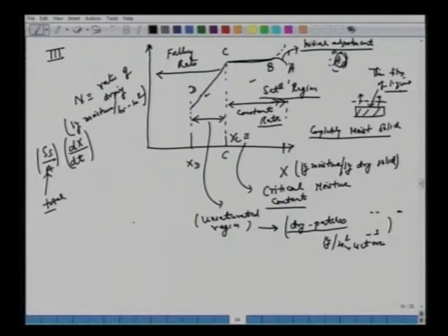As far as the mechanism is concerned, whether the saturated region or unsaturated region, most fundamentally the two mechanisms are the same. What we are seeing here, the decrease, is an artifact of the area which we have chosen. It's the total area. Mind you, because there are patches, the actual wet area is getting smaller. So if you measure per wet area, the two will be the same.